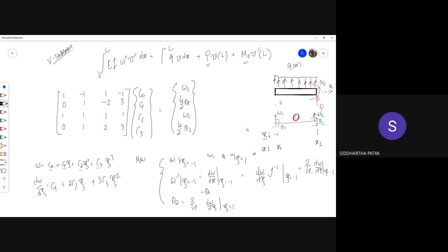We are still away from the load vector or the stiffness matrix or the degrees of freedom. What we are doing is just getting an alternative representation. I can represent a cubic equation in general like this, but if I were to satisfy these conditions, these are general coefficients and these are the degrees of freedom. So how do I represent W in terms of degrees of freedom? Whatever polynomial would be the coefficient of the degree of freedom, we would call them shape functions. So what you are trying to do here is get the shape functions.